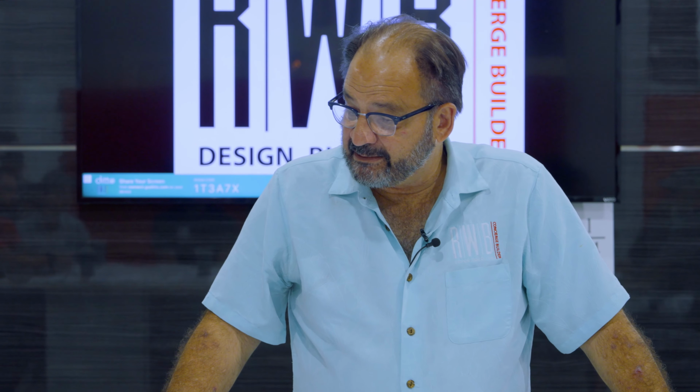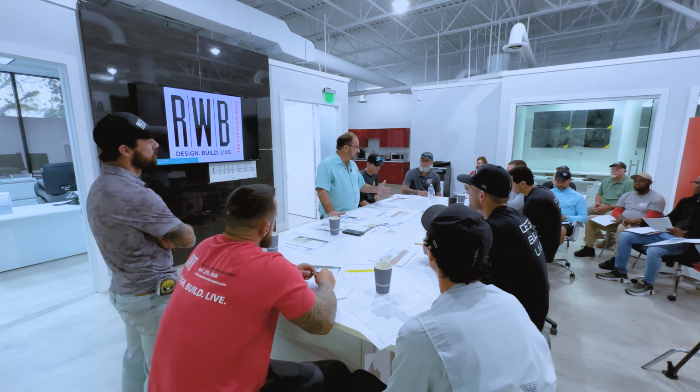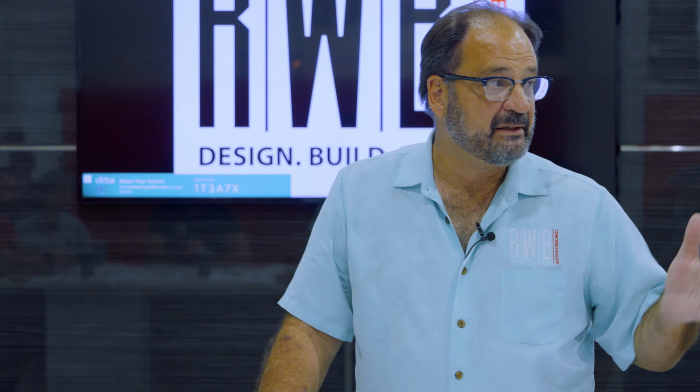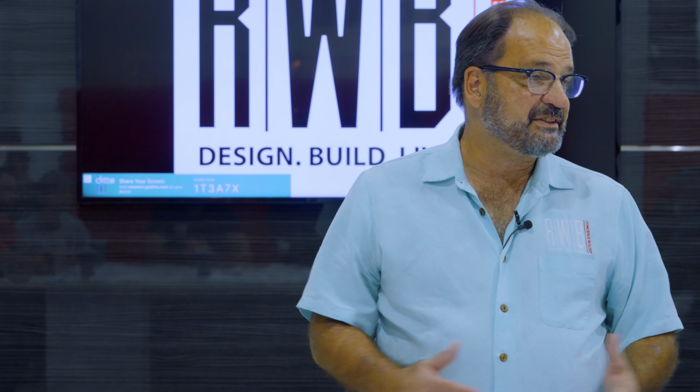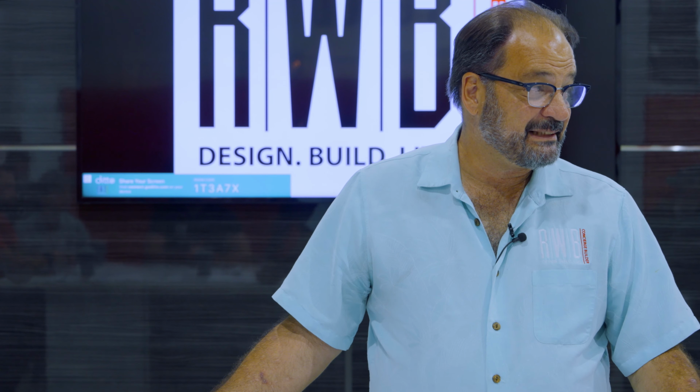So there's a separation. And again, that means that separation has to be not only within your property, but if your neighbor has a well also. So for example, if your neighbor's well is right next to your property line, even though it's not on your property, it's within X amount of feet of your property line. You want to make sure when you do your plan, and the health department will regulate this, you're so far away from his well, from his septic, you have to consider all the adjacent properties as well as yours. Has everybody kind of got that?